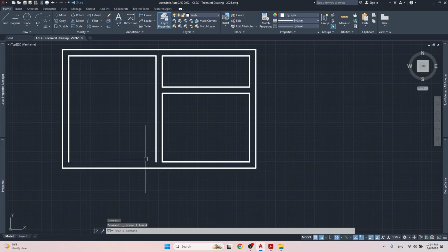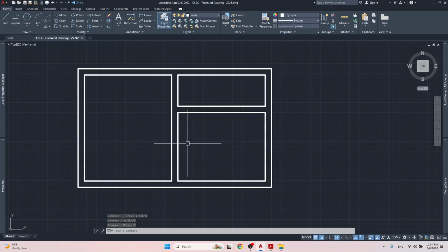All right, let me see. Okay, we're just checking that there's not two lines on top of each other, and if there were two lines, it doesn't really matter. So these are my foundation walls. These are underneath my walls of the house. And then we need footing lines, the lines for the footing, for the continuous strip footing. So underneath each of these walls, there's a footing. So the footing is going to be shown as hidden lines.